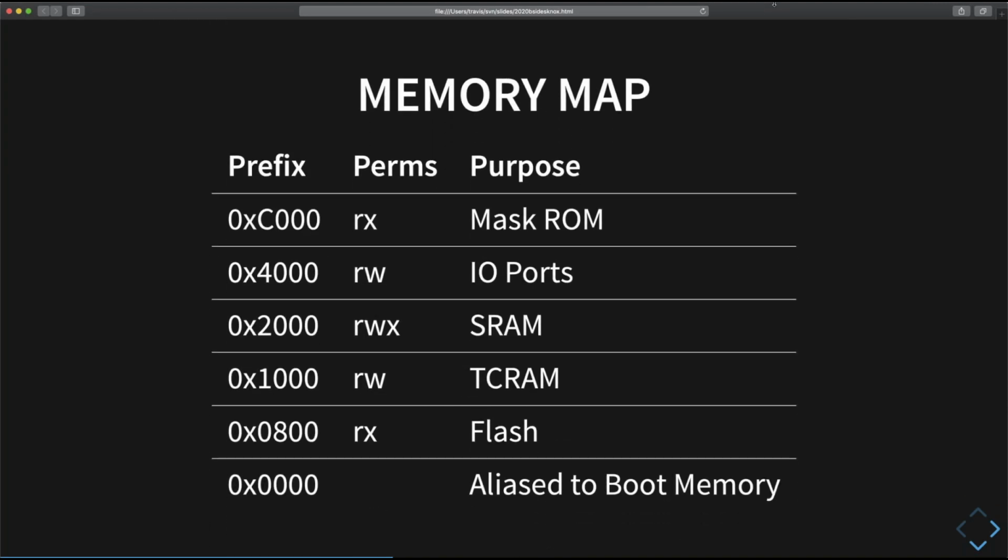Travis, maybe just to cover it for people, if they don't have a PoC||GTFO article to reference the memory map, how might they find that in documentation? Oh, yes. So this is always in either the datasheet or the programmer's guide, which is sometimes called a family guide. It will be unique to your chip, or at least to the chip's family. And it will tell you which pointer goes to which location.